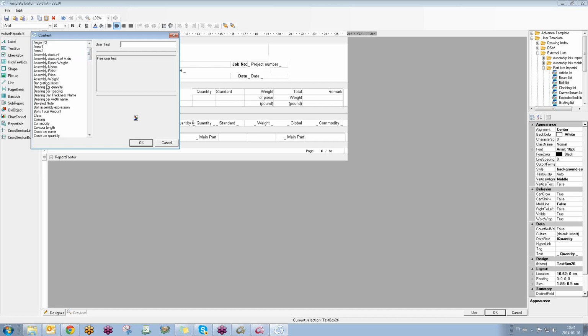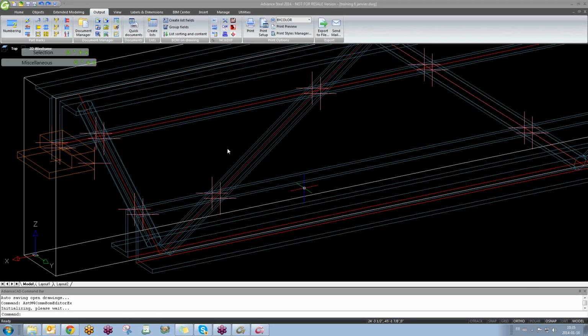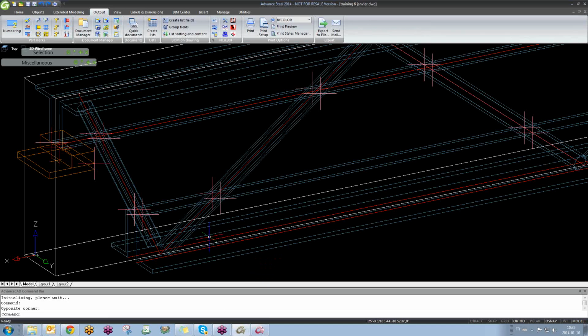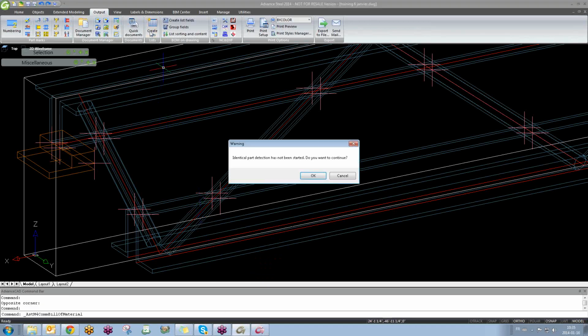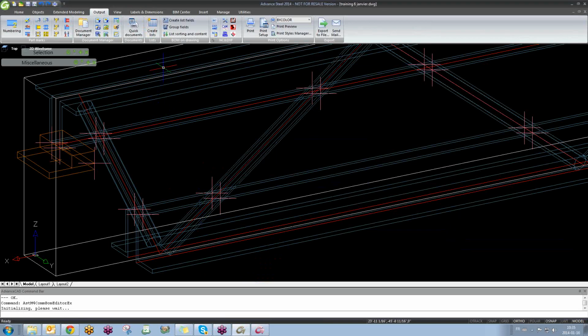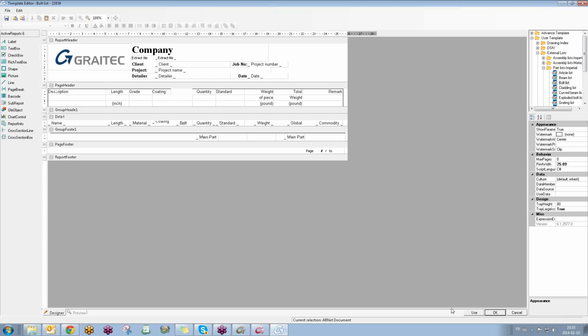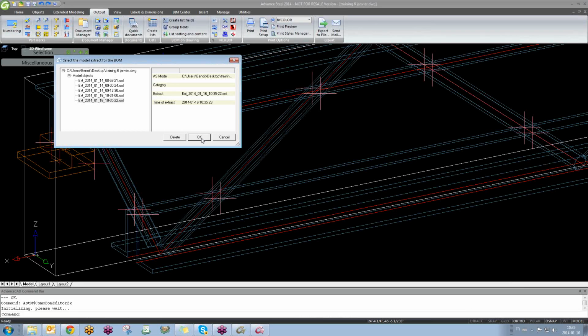If you look, this is what I have. I have this little piece of plate showing up in my form. So let's use this. The way it works is I modify the drawing settings so that Tekla can recognize bottom flange, top flange, webs, table plates, and everything. So if you don't have the model specified for table plate, you won't get that in your drawings. All right? This is especially important for beams.